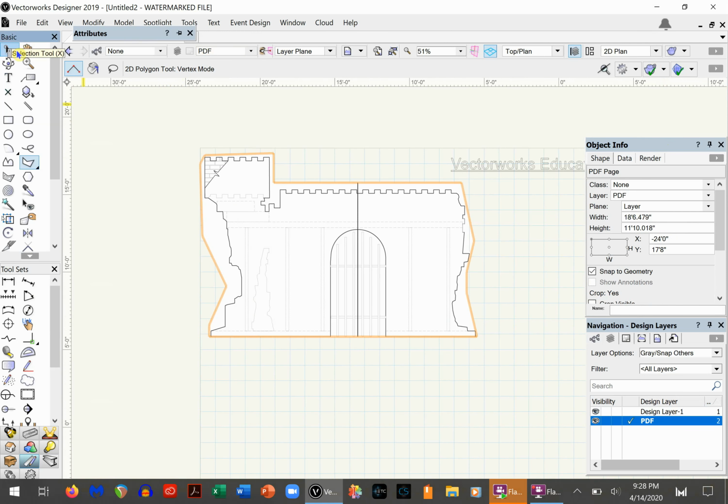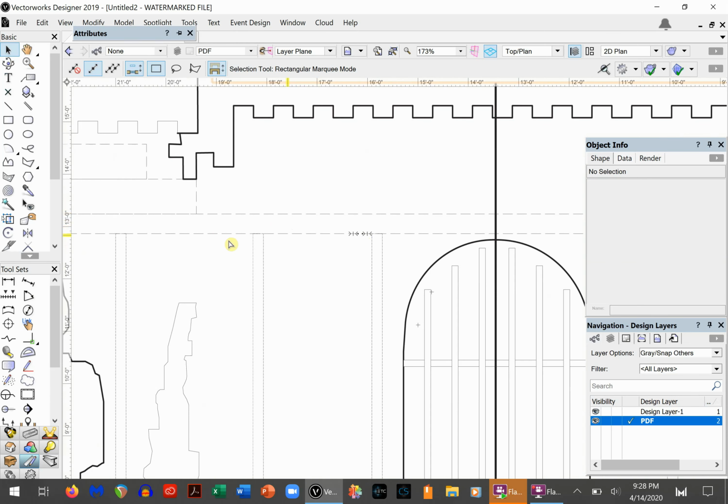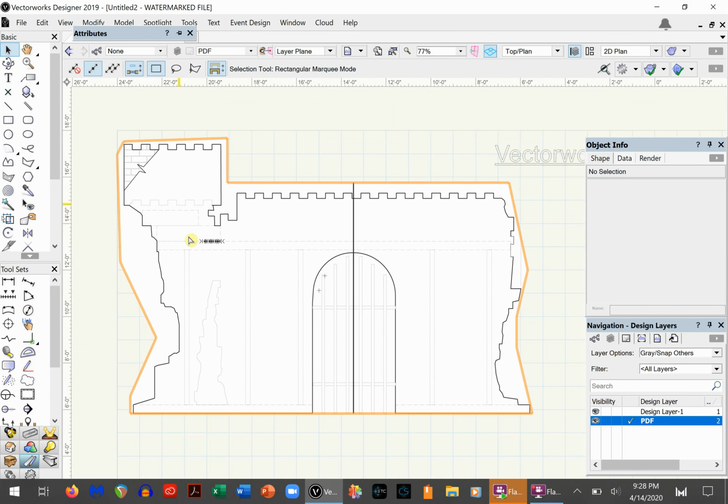Yeah, that's pretty good. So the only things that are wrong here now are, like, this was a section cutting plane line. I've got a portion of it that I can't get rid of using this method. And there's some other stuff, like the hidden lines showing the stud walls and platforms behind. Those I don't really need. They might get kind of annoying to have in existence behind my frame plan or my cover plan, maybe.